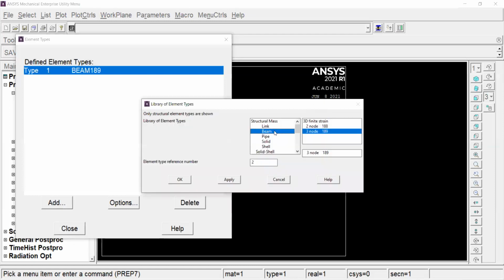We'll have another beam type, and we'll define the plate element. So when we're working with beams and plate elements together in one model, instead of defining it as a solid and then choosing a quad 4 node or 8 node, we'll select a shell element, which is basically the same thing as a plate, and we just define the thickness.